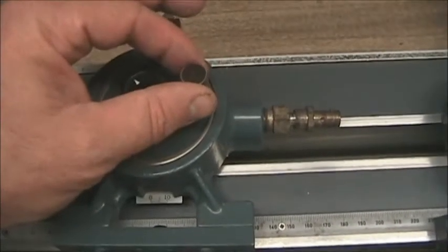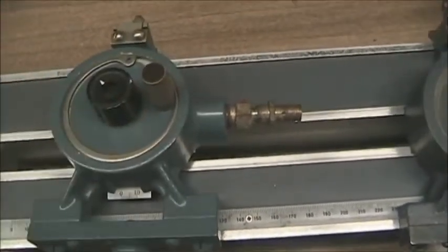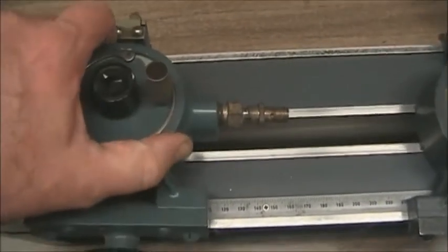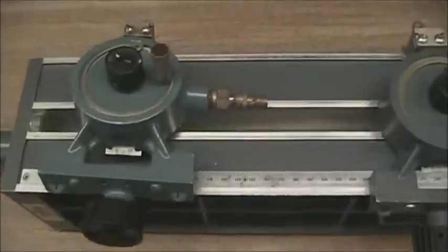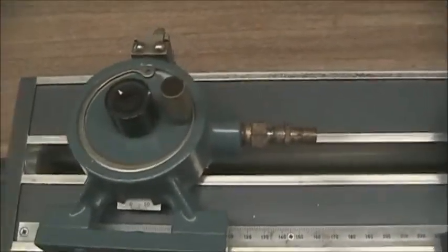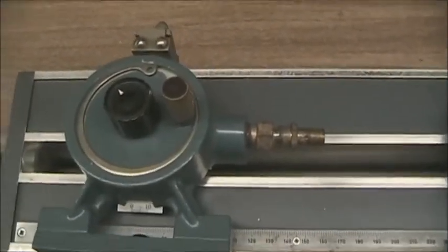This little knob here is actually adjusting the depth of the probe. So we don't want to get the probe too close to the center conductor, certainly don't want to touch it, and so by adjusting the probe depth you could adjust for sensitivity or low signal level.